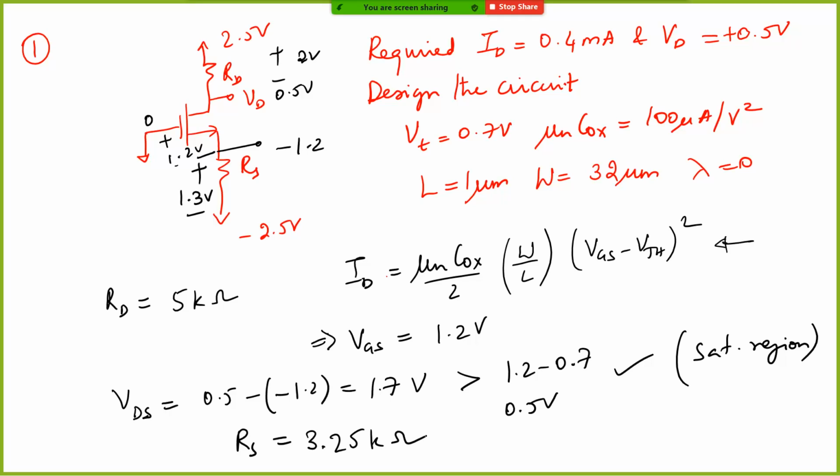So the important thing to note in MOSFETs is that the gate current Ig is 0 always. At least at low frequencies, the gate current is 0. This is in stark contrast to BJTs, where there is a finite, non-zero amount of base current. And because Ig is 0, you can always assume Id is equal to Is.